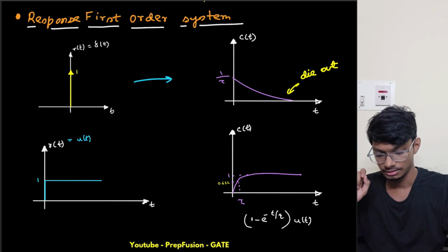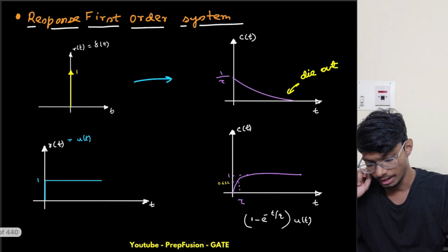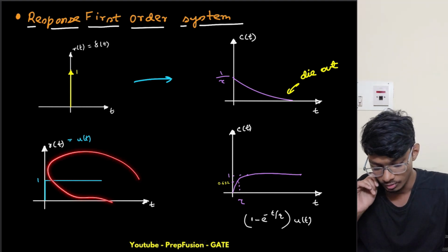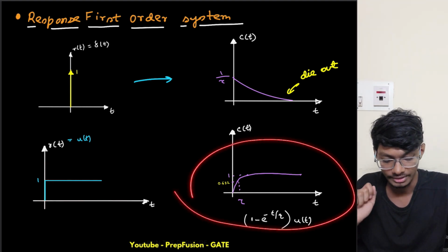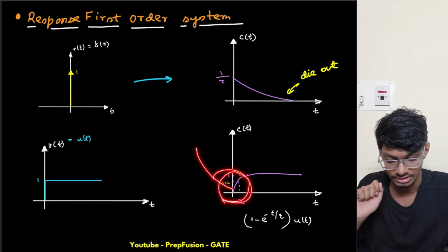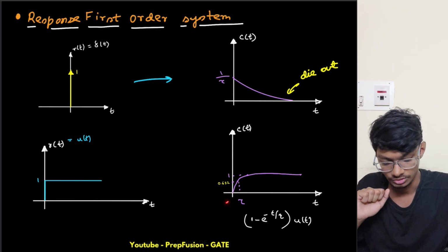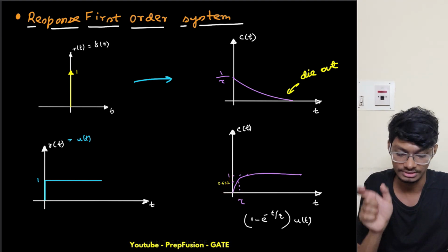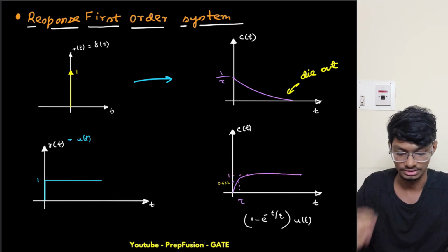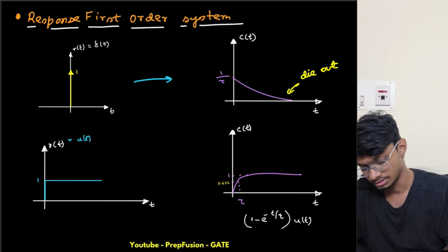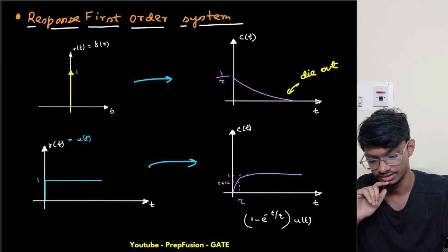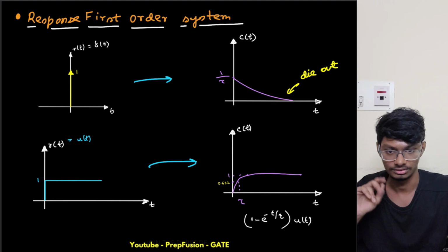Okay, and now what do I have here? I have a unit step input, and due to a unit step input, I am getting again an exponential, right? And this represents the step response, basically. So here I have a transient, it is going from one steady state to another steady state, and then it is dying down and reaching steady state, right? Stable basically. So this is how my step response and my impulse response look. If you integrate this one, you will get this one, right?